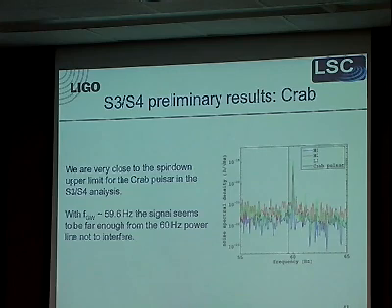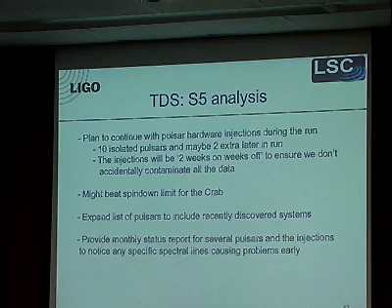Well, the demodulation doesn't actually take it into the power line. It's not that large of a shift. Right, but you're within a half a hertz of a power line that has one or two hertz sidebands, so I don't know how you're getting out and away from this. Doesn't look like it. Power line's very narrow. Power line has 1 or 2 hertz sidebands which are upconverted from low frequency noise. If you're integrating over a very long period of time, those might disappear when you integrate over a longer time. And they integrate because you're modulating frequency.